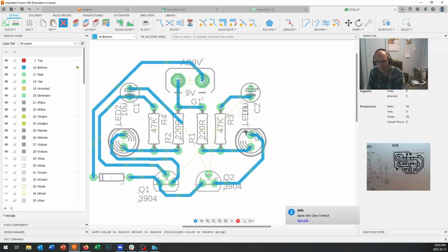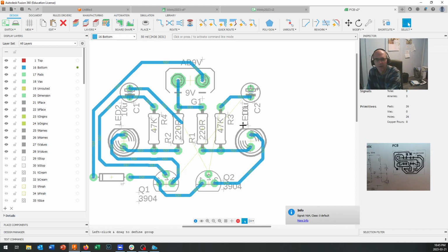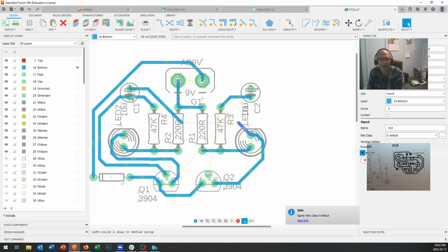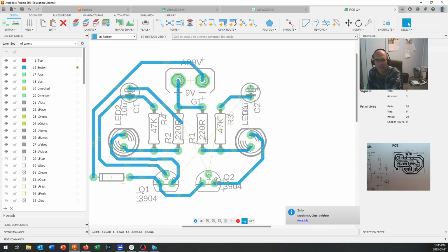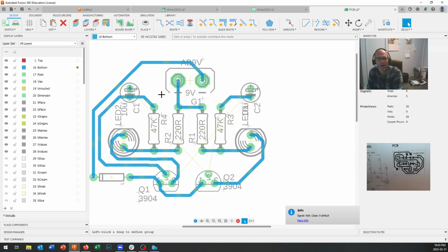Just a minute. Control Z that. Now you'll see that when I did that, it made the air wire disappear. Be very careful to not let that happen. You've got to watch where that air wire goes because this right here still needs to know that it needs to connect to right here. Now it may redraw the line somewhere else. Okay, it still drew that line down to there. That's perfectly acceptable. But when you delete a part right in there, make sure it doesn't get rid of that air wire. Those ones need to connect right there.